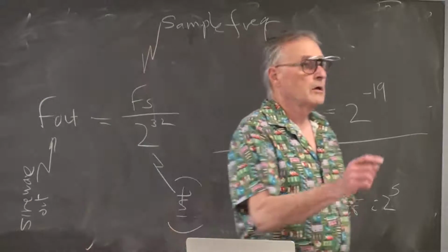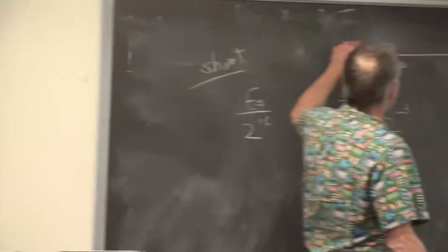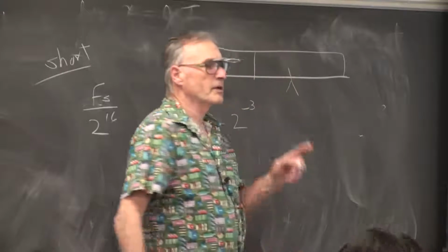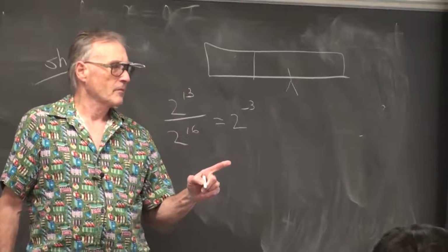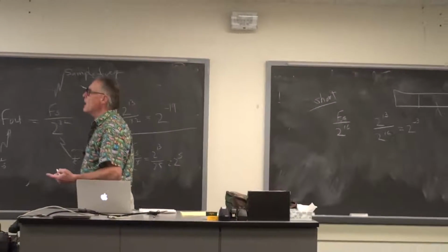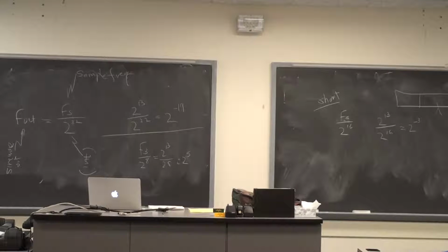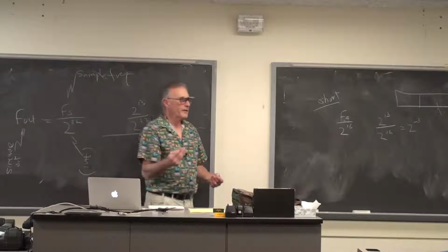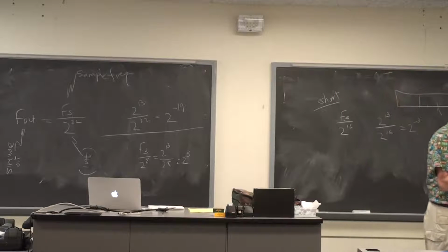So you need the extra bits in the register, in the variable. You need the extra bits in the variable to give you sufficient accuracy in the synthesis. They're not used directly as an index. They're used as fractional index values. They're used as tiny fractions of the index that allow you to step much more slowly and carefully through the table.